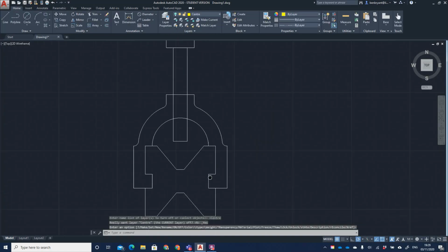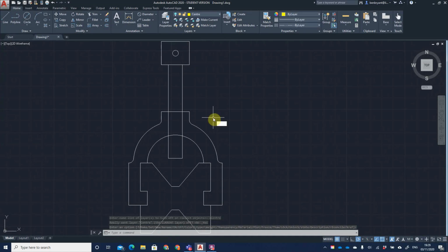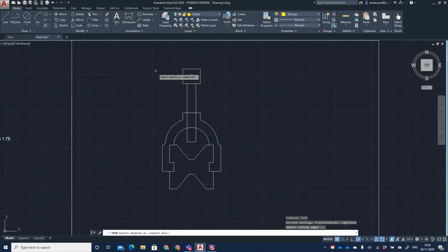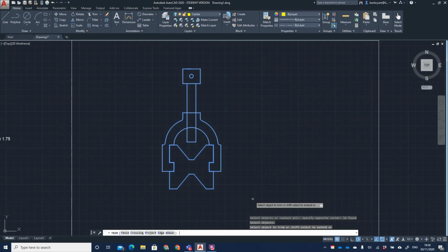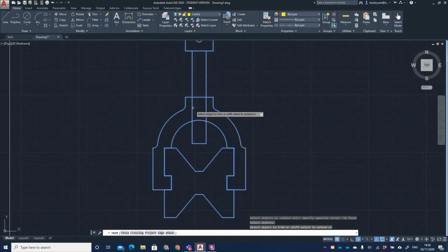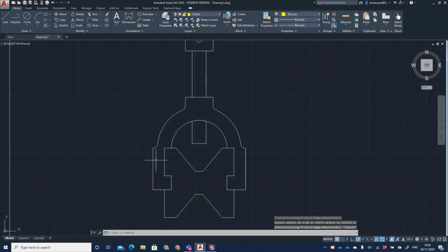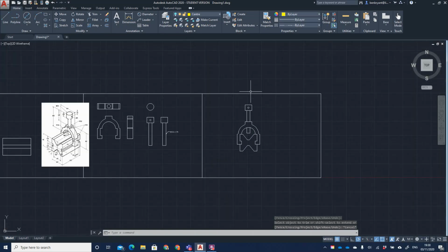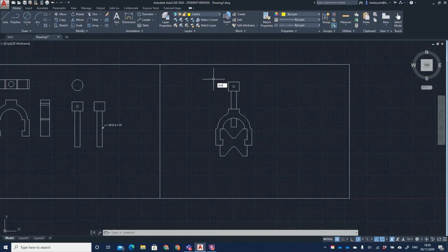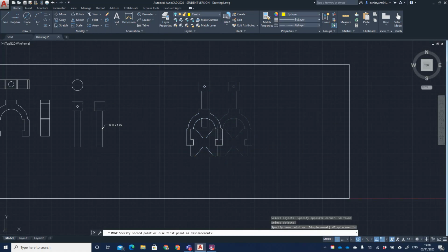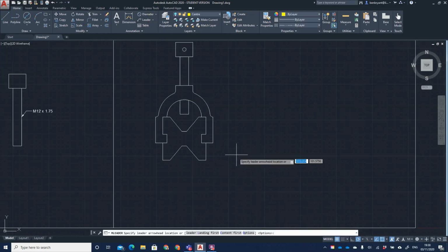That's what I do. It's got to do a bit of trimming because you actually see the components inside. So I'm just going to trim, select all. Okay, come along, trim out the components that I won't see, like so. Everything else I will see. I can actually say that's the first part of my drawing. So I can actually move it a little bit over to one side. Nice and simple. Then you come along and do some leader lines.